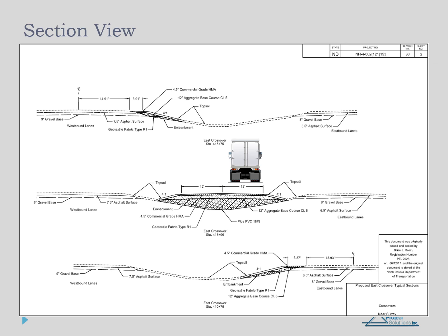Lastly, we have section views. This view is the cross-cut and would be like looking at the rear of a truck. Here we can see the slope of the road and of the land at different stations. It is not uncommon to have multiple section views, each at different stations, so we can get a sense of the overall plan.